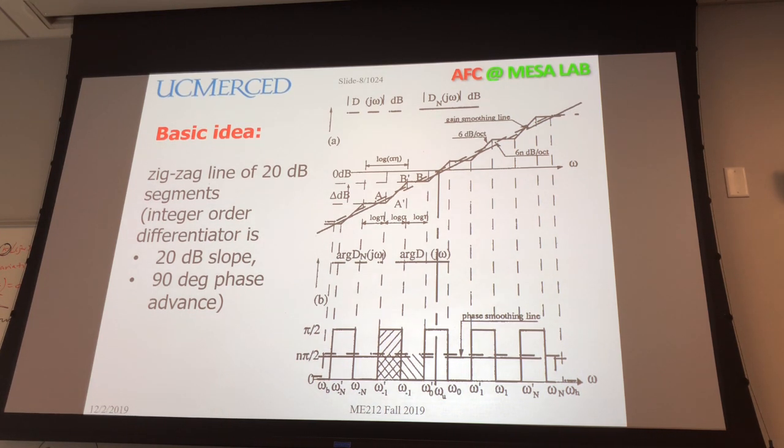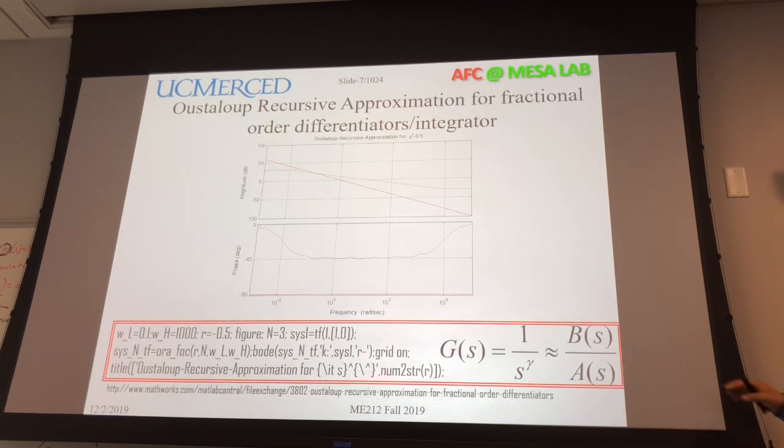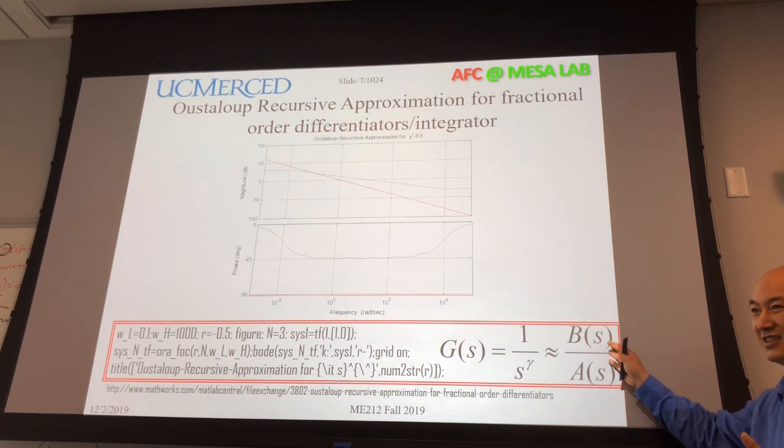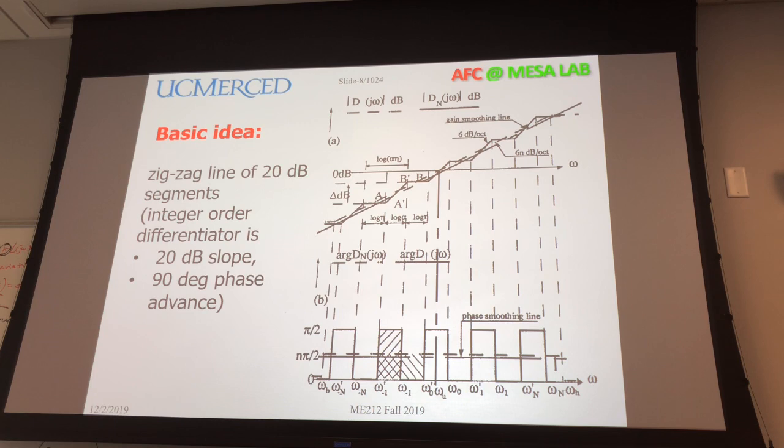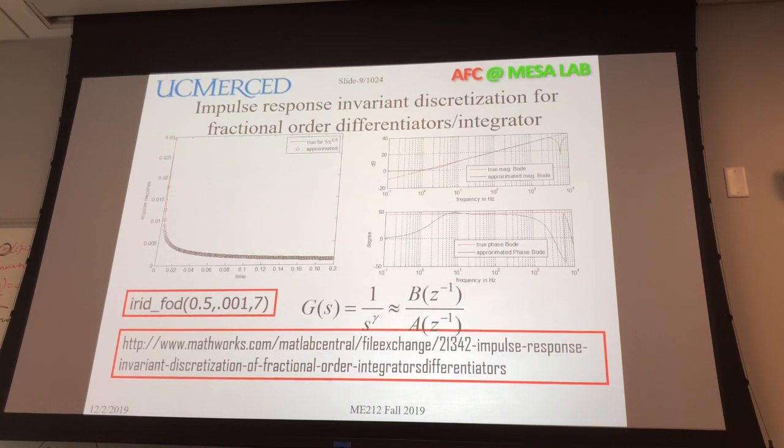So in fact, by doing that, this one has a product of poles and zeros, simple pole, simple zero, no multiplicity. And they are interlaced very nicely, recursively. Then it is also minimum phase and stable, okay, stable. I invented this code. I wrote this code. So you can just give the order, this 0.01 is your sampling period, okay? Sampling time, sampling period. Then this is the order of this polynomial.